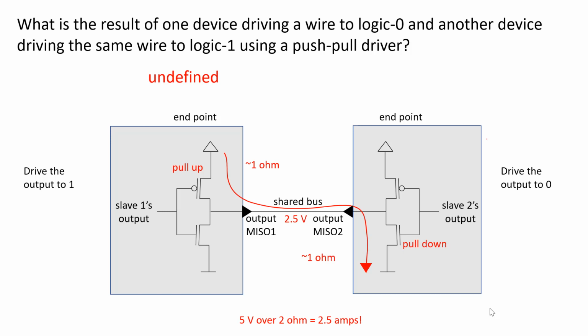Yes? So in order for this one to work, they both have to be 0 or they both have to be 1? Yeah, that would work, but even then it's not good to do that. Generally speaking, you should have one driver per signal. So every signal should only be set by one thing, but it can be read by multiple things. Oh, by the way, just to be clear, in SystemVerilog, this would be like an always statement, for instance, and this could be like an assign statement, each one representing a circuit that's driving an output. Okay, so what is the answer?